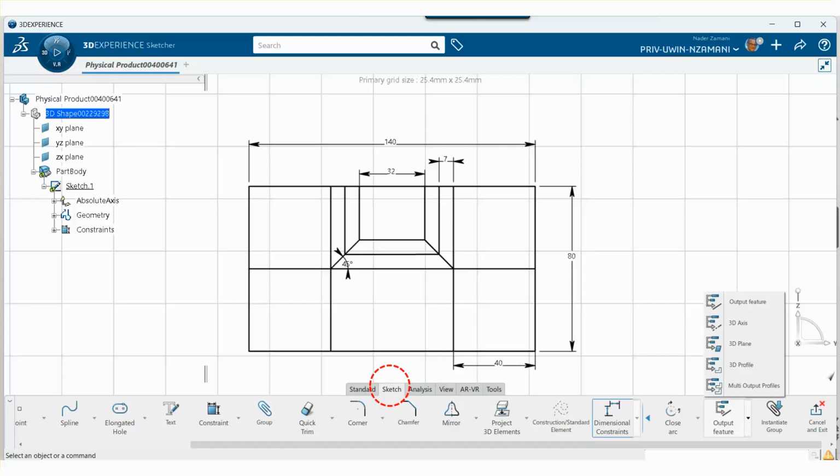Now, there are different ways of doing this problem. Among the different ways, for example, I'm suggesting here one possibility is to create the output profile and then use those output profiles. We'll actually make a sketch like that on that face, no problem, but create output profile and then extrude those output profiles.